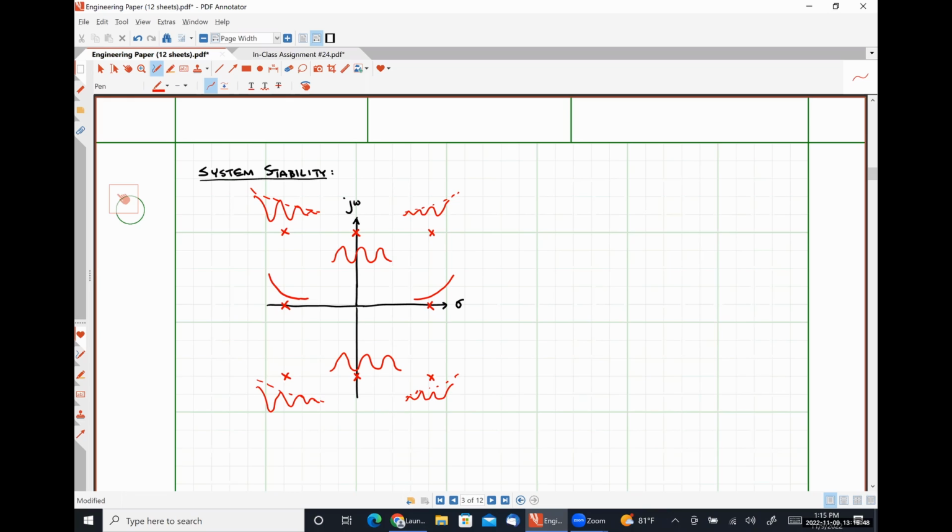Practically, this is actually quite bad. The reason why it's quite bad in a practical sense is because things like process variations, power supply ripple, perturbing your system in any small way can actually push you over into instability where no input signal or thermal noise is capable of generating oscillations. So if you design a marginally stable system, what you will likely observe is that you have intermittent periods of oscillation that are a real pain to troubleshoot, because you can't tell why they're happening because they are intermittent, non-periodic by their very nature.